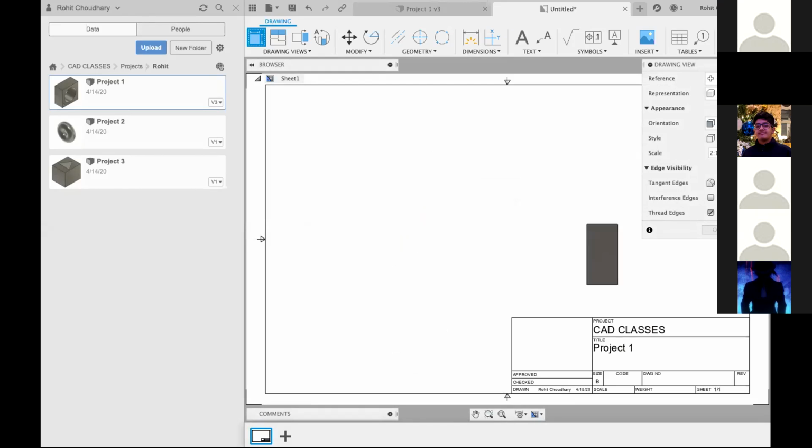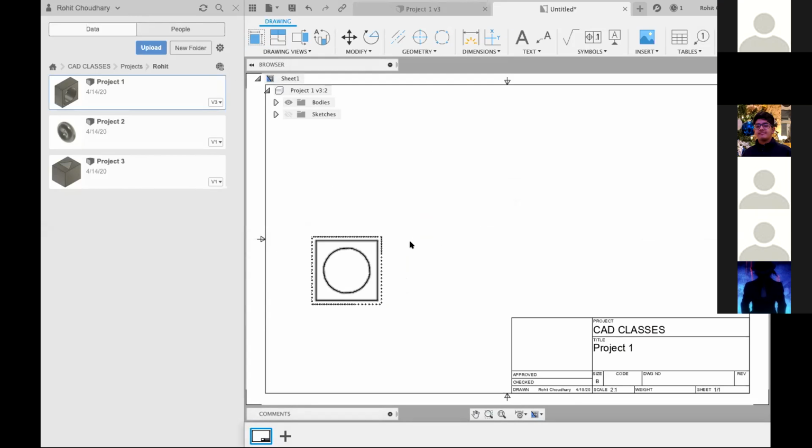Yeah. Okay, so I'm just going to choose right because that shows the most detail in my object. I'm going to click wherever I want to keep it. Once you've done that, just hit OK. You'll see that it creates a drawing of that view, a 2D drawing of what your 3D object looks like in that plane. Once you've clicked OK, just tell me and I'll move on to the next step. I clicked OK. Okay.